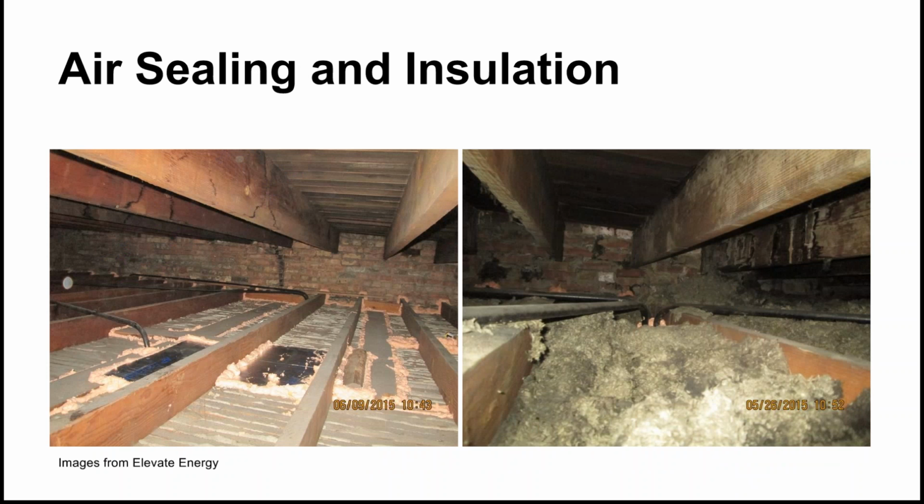Something that's really important with single-family homes is looking at air sealing and insulation. First I'm going to focus on air sealing. Basically, air leakage is caused by two things. It's caused by a hole between the inside and outside, and it's caused by a pressure used to push air through the hole. The hole is pretty self-explanatory. It occurs at windows, doors, seams like the wall and floor cavities, recessed sites, all sorts of things, and also at intermediate zones like attics, basements, crawl spaces.